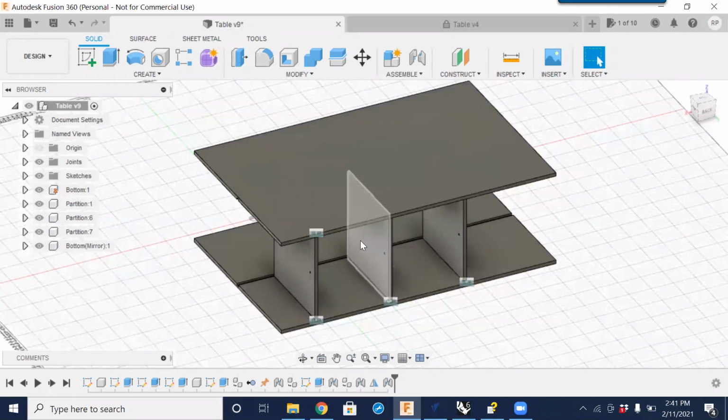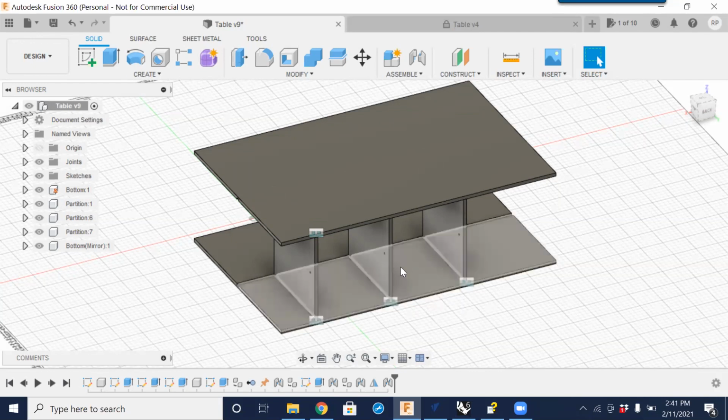I did that not so much for the purposes of creating the assembly in the drawing. I did that to make it easier to assemble when all the parts are cut out, so we don't have to pay attention and measure which is the top and which is the bottom. Because if I didn't have those perfectly aligned and centered, down an inch, when I go to glue this all together, I would very most likely put one of these parts in upside down. But by having those constrained to the midpoint, it doesn't matter.